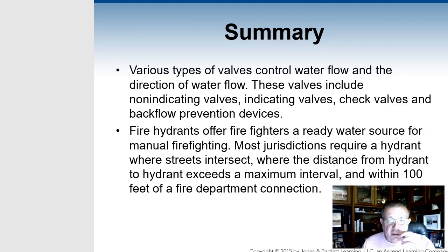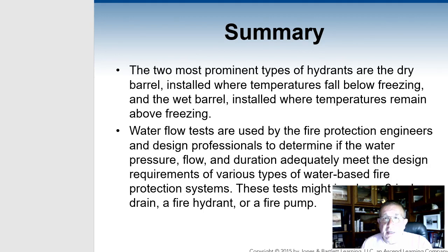So you've got to look at the valves. You've got to look at the indication that's going on with the hydrant itself, how much water is coming in. You've got to look at the hydrants and how firefighters are ready to use manual firefighting apparatuses, meaning fire pumpers and that. And do they have enough water to put the fire out? Take the next big fire that you're on and calculate how much water you use during that fire. You might be surprised how much you have and how much you don't have.